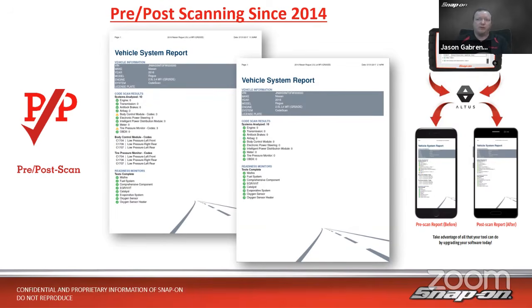Now, what you do when you do a pre-scan for the vehicles, it will scan all the modules on the vehicle and return any codes that are in those modules. This is especially important for vehicles with ADAS. Some vehicles with ADAS may have a code stored, but it may not turn a light on the dash. It may not have a light even associated with it on the dash. So maybe it just might simply not work, may have a malfunction, and we may not know unless we scan through all the modules. Instead of just simply going one module at a time, let's scan them all, right?